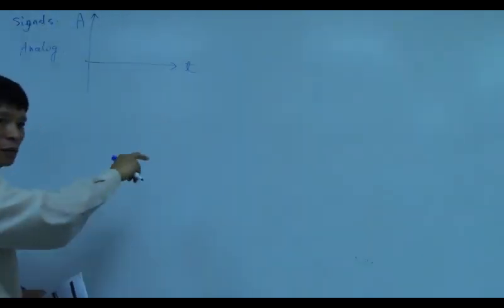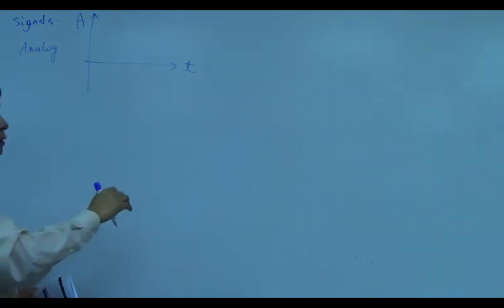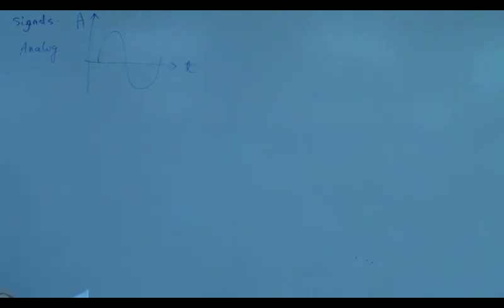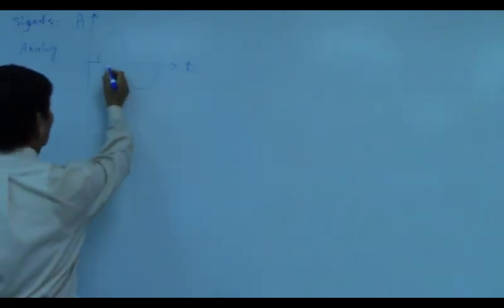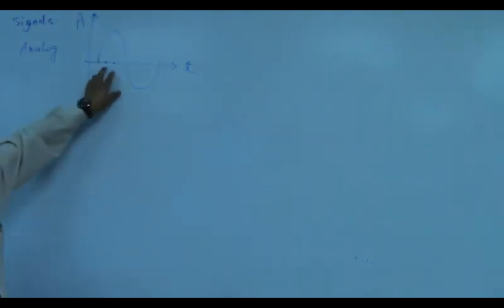in time it is continuous. The amplitude is also continuous. For example, it looks like this. Continuous means no matter which 2 points you give me, I can always find 1 point in between that has a definition. No matter how close these 2 points are. So like this, from 1 second to 2 seconds, I have 1.5. From 1 to 1.5, I can have 1.1.